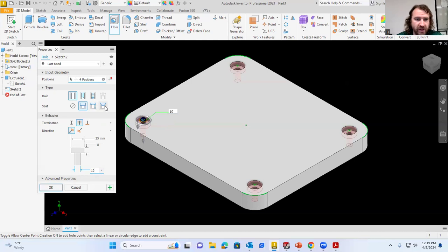And the same is true if you're given one. Typically, countersink is the other version, but spot face works the same way as the counter bore. It's just much skinnier, and you can see there's already errors there, right? But the countersink is the same idea. With countersink, you're going to have what is the hole clearance, what's the angle. Maybe the countersink angle might be different depending upon the bolt, and then the diameter here.